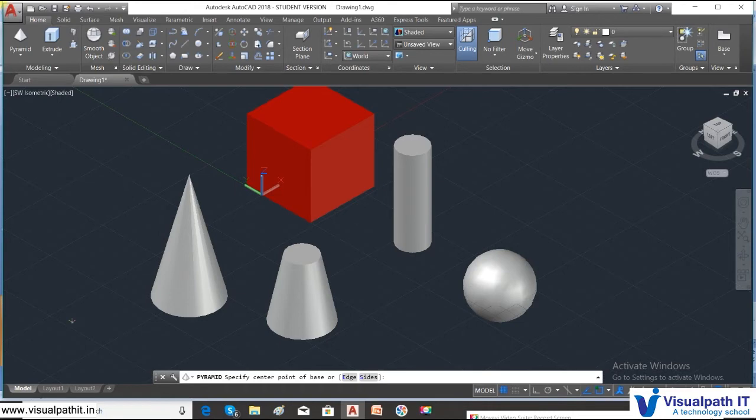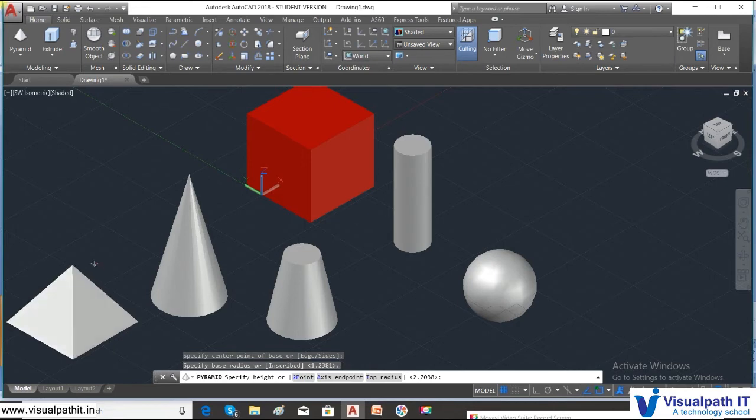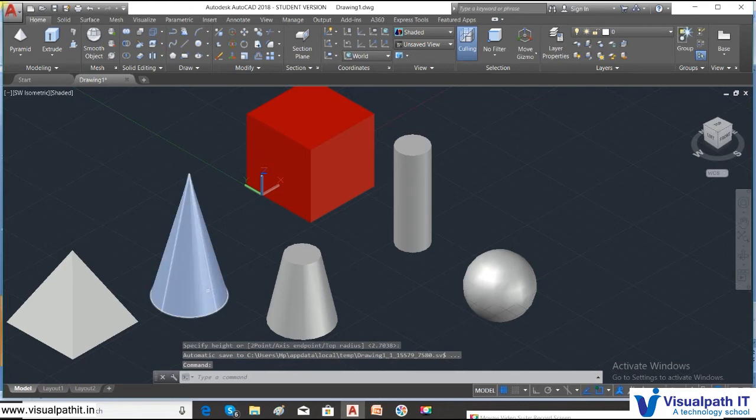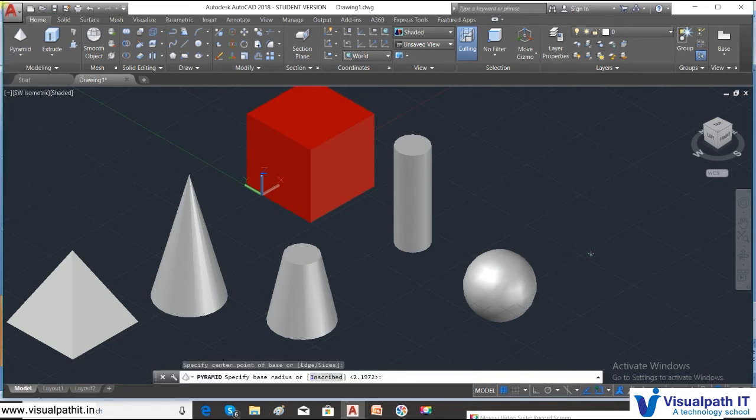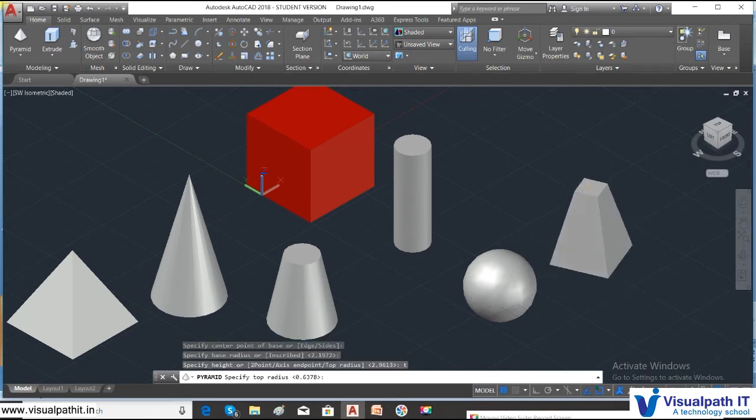So pyramid, center point of the base, it's a polygon type. So inscribed or the circumscribed, base radius it's asking. Base radius you can specify, then you can specify the height. So it's a pyramid. So if you want a truncated pyramid, give the pyramid option. Hit this base radius. Then you have this top radius, T enter, top radius. So you can specify the top radius also. And then you get a truncated cone.